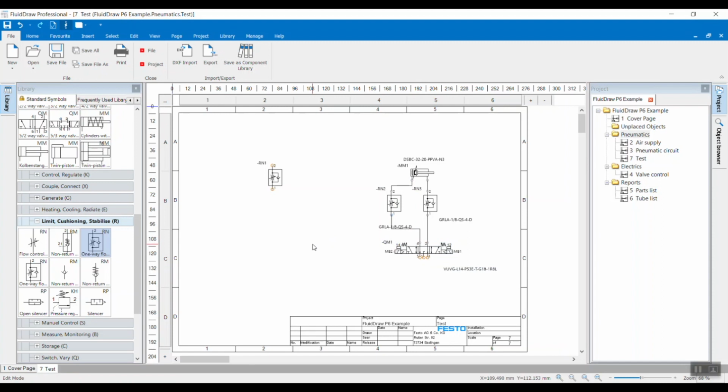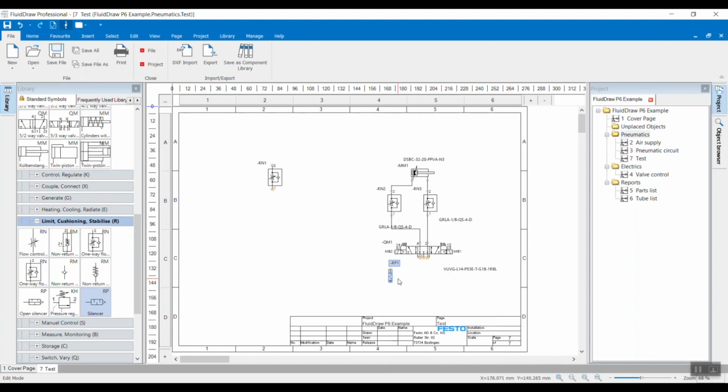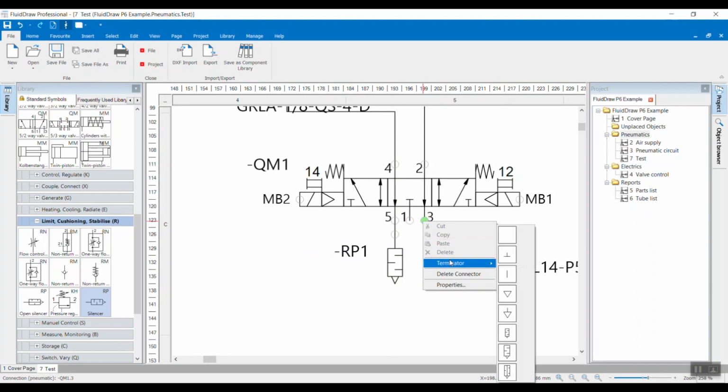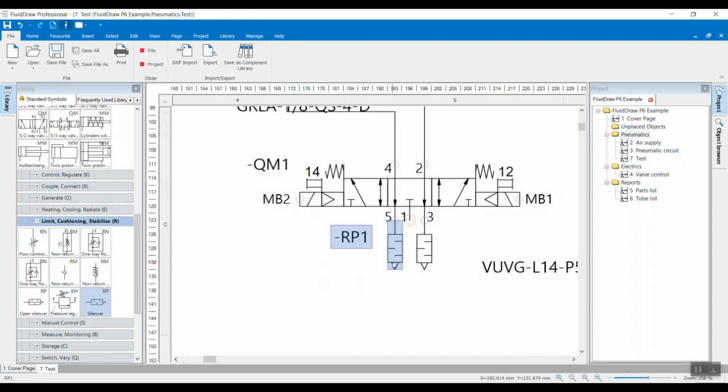Now when it comes to silencers and plugs for ports, there's a number of ways of doing it. As you can see here in our library, a silencer can appear. If it is dropped down, what we can do is rotate it. Move it along, and as you see here, it's now a component that has its own identifier and it is separate. What you can also do is right click on the port and just add a silencer in. This way it becomes a sub part of this component and it will not show up in any bill of materials. If this is something that you do in your factory or your standard operating procedures, that they have just a fitting cabinet and you just don't want to spec every single little thing on your drawings.